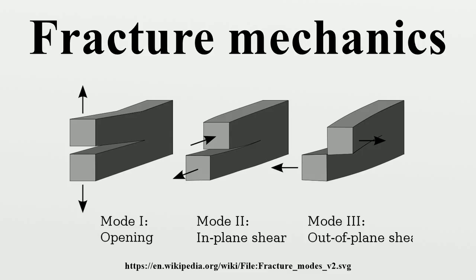Griffith's theory provides excellent agreement with experimental data for brittle materials such as glass. For ductile materials such as steel, though the relation still holds, the surface energy predicted by Griffith's theory is usually unrealistically high. A group working under G. R. Irwin at the U.S.